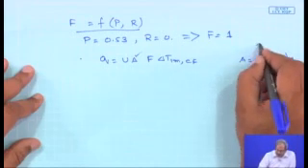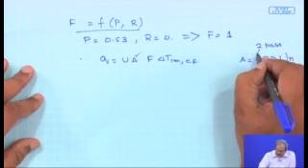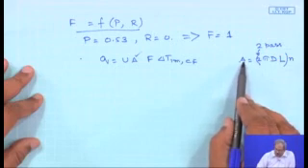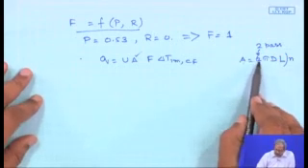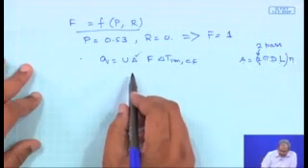Since it's a 2 tube pass heat exchanger, that's why this 2 comes in. So, the total area available for heat transfer is twice pi d L times n number of tubes.